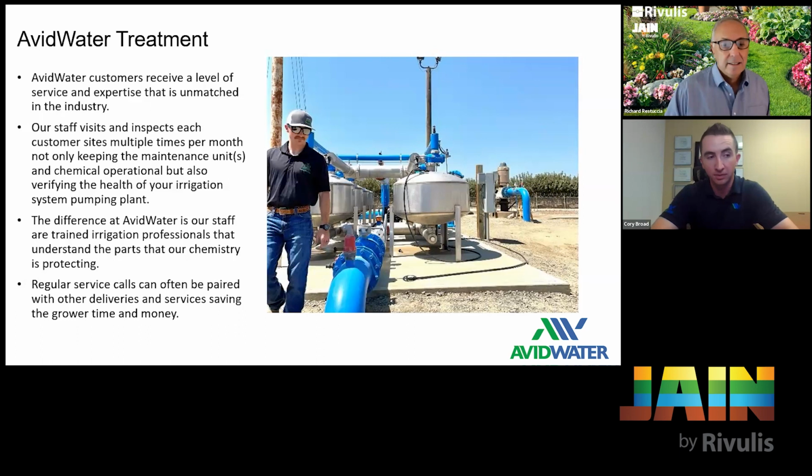We're going to write down flow meter readings for you, and make sure that you're on track for the chemical you've used. So if you've used 10 gallons, I'm picking a fictitious example, of chemical across 100 acre feet based on what the flow meter says, is that still correct for the prescription? It's really just about staying on top of those things. And when you look at the pressure of the system, if every time you go out there it's 38 PSI at this flow rate, and things have not changed, you feel comfortable as a service provider and hopefully as a grower.